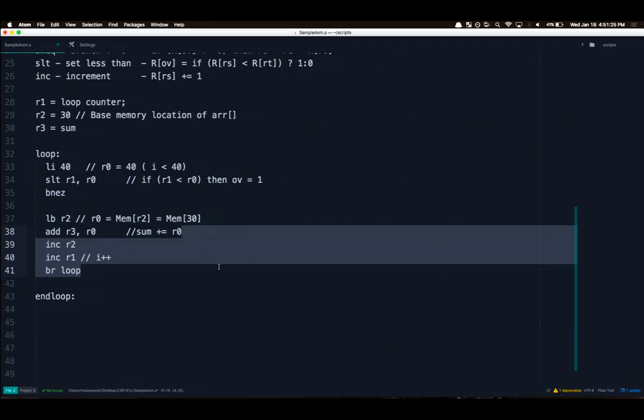Why do you just increment the memory address by 1? Wouldn't you need to increment by 4 instead? So 4 is for a 32-bit system, whereas this is an 8-bit system, so we're just incrementing by a byte. So basically this strategy is to reuse one register, whatever operation it is. Yeah, that's if you're constrained on registers. If you have 16 registers, you can definitely do the programs and won't have to worry about registers. But if you had 8 like me, then it's going to get a little tough.